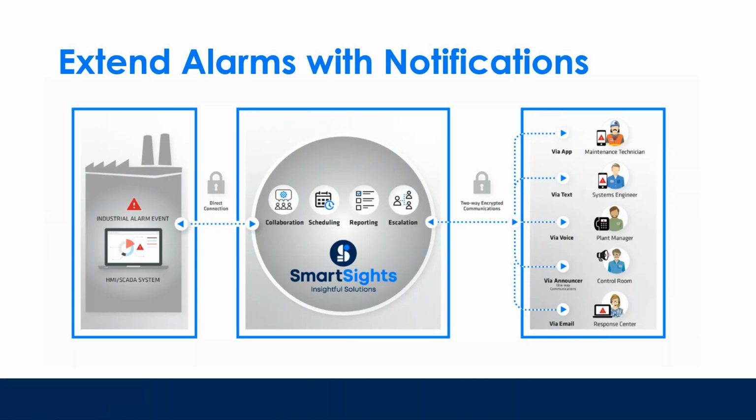The first one is remote notifications, and people in the audience may know this as the Win 911 product that taps into in-plant alarm and event systems like Factory Talk or InTouch or iFix, or even directly into controllers and equipment. And it takes the alarm conditions, the process deviation conditions that are happening in these systems, and it intelligently routes them remotely to all the different critical roles that are involved in these industrial processes.